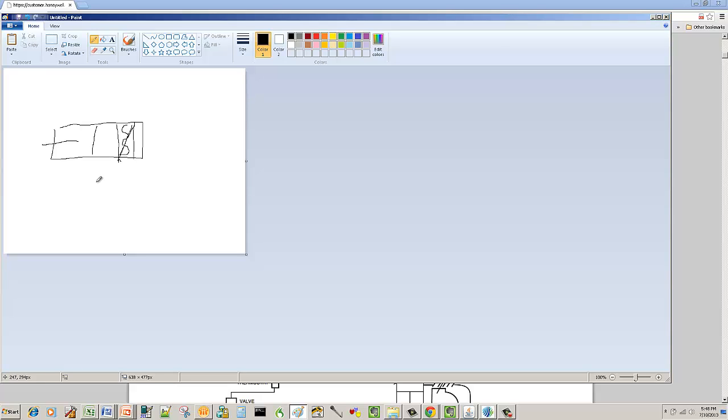Now here's the thing. Typically, for cooling, the method we use is to introduce 55 to 65 degree air, and you rely on air changes. The air changes are going to change that temperature because your heat floats to the top, your cold air settles on the bottom, and you're changing the volume of air. Maybe you're looking at 6 to 8 air changes. Maybe you're in a hospital, you're looking at 20. But you're changing the volume of that air. That keeps particulates and pathogens out of the air, but it also helps cool a space down.